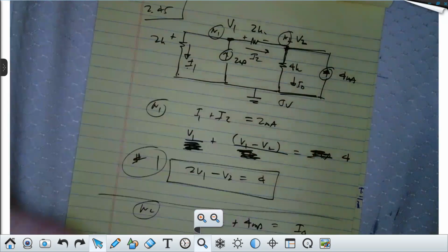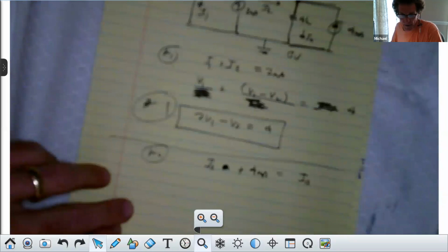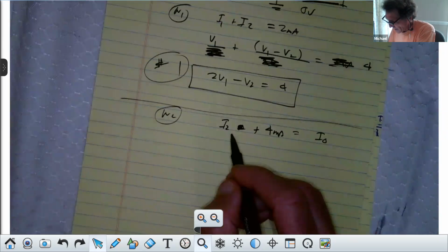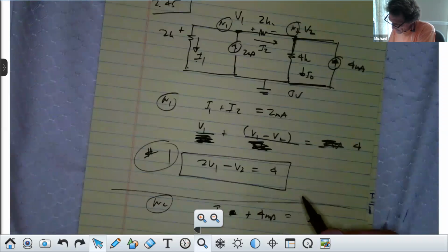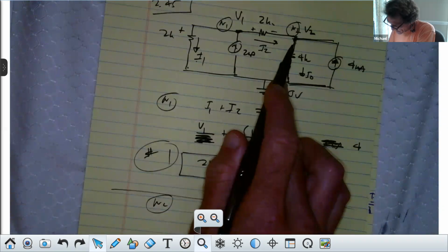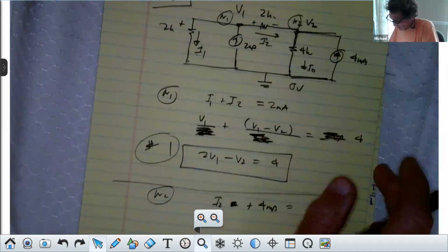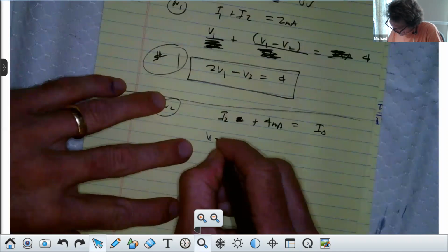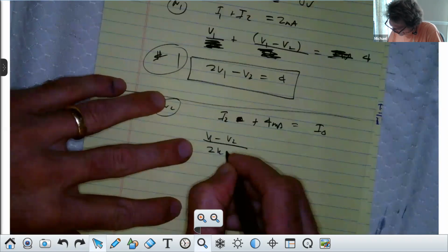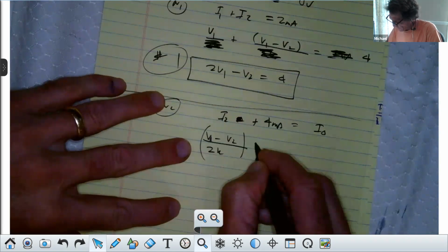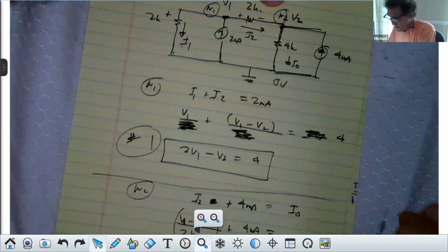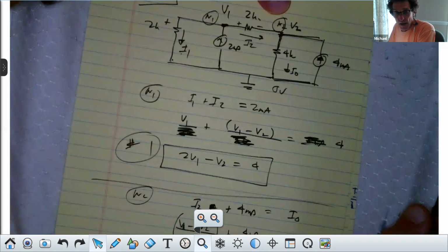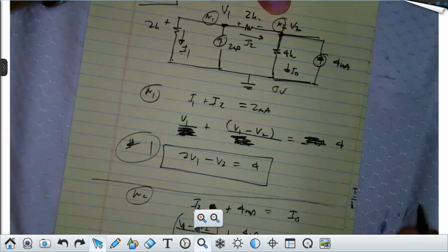Okay. Next. What is I2, class? V1 minus V2 over 2K, right? V1 minus V2 over 2K. Don't forget that. Plus 4 milliamps, right? Equals I naught. What is I naught? V2 over 4K. Right. Y'all got that, class?